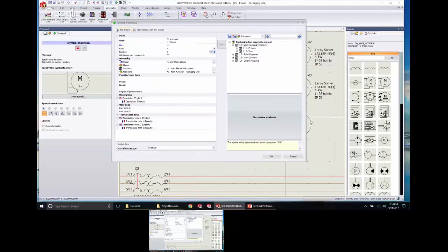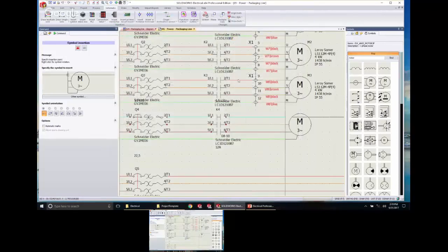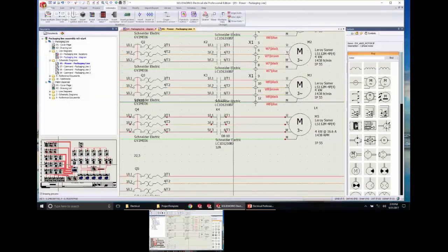Excuse me. And again, it's trying to create a brand new one, right? M9. But no, I know I can also use these class filters. Okay, so you can do same base class or same subclass if you're using a subclass. So here, M5, no, let's do base class. There we go. There's that M5 new motor. Hit OK, and again, I get all that information.